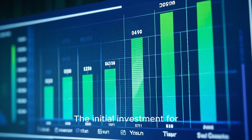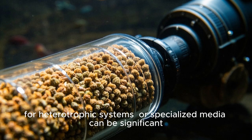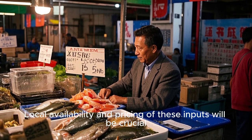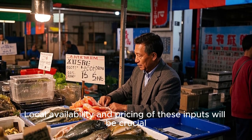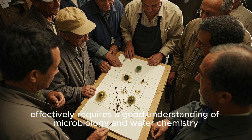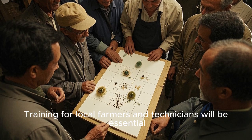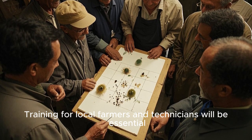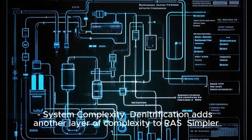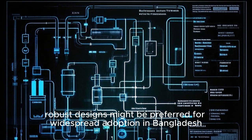Cost-effectiveness. The initial investment for denitrification systems and the ongoing cost of carbon sources for heterotrophic systems or specialized media can be significant. Local availability and pricing of these inputs will be crucial. Technical expertise. Operating and monitoring denitrification systems effectively requires a good understanding of microbiology and water chemistry. Training for local farmers and technicians will be essential. System complexity. Denitrification adds another layer of complexity to RAS. Simpler, robust designs might be preferred for widespread adoption in Bangladesh.